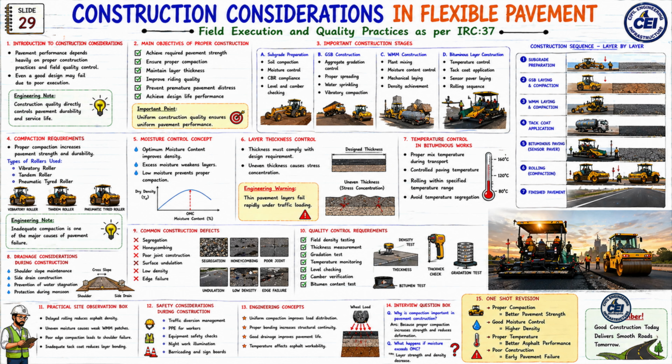Now let's look at the 14th topic. 1.4 Interview question box. Q. Why is compaction important in pavement construction? Answer. Because proper compaction increases strength and reduces deformation. Q. What happens if moisture exceeds OMC? Answer. Layer strength and density reduce.